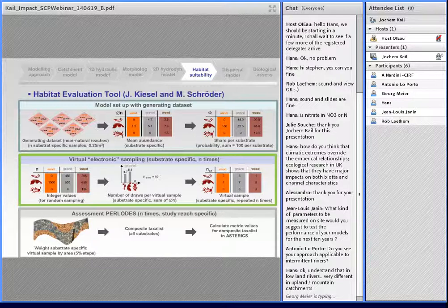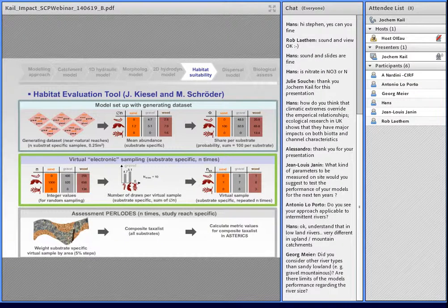And we faced a little bit of problem to model substrate conditions, because all the modeling of the sorting of the substrate, especially in mixed gravel sand systems, is not that well established in morphodynamic modeling. So this is kind of problem.